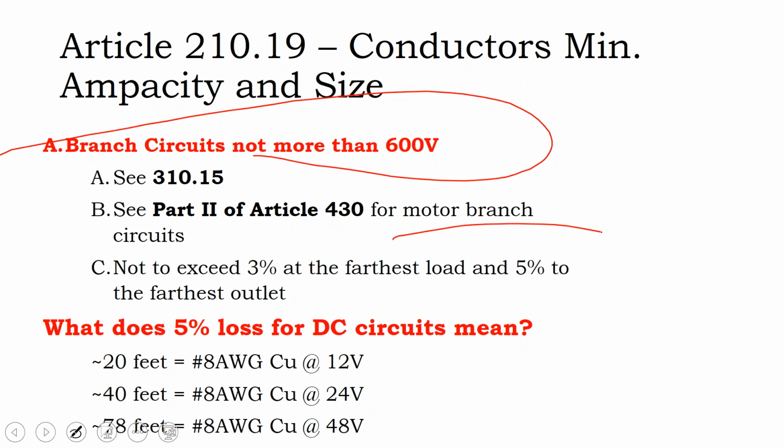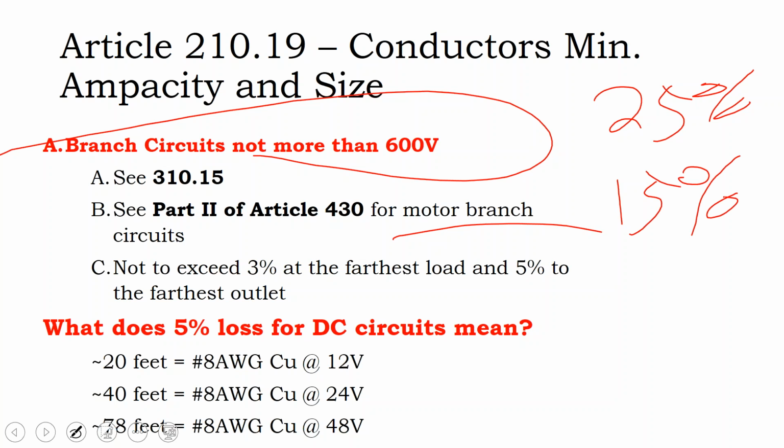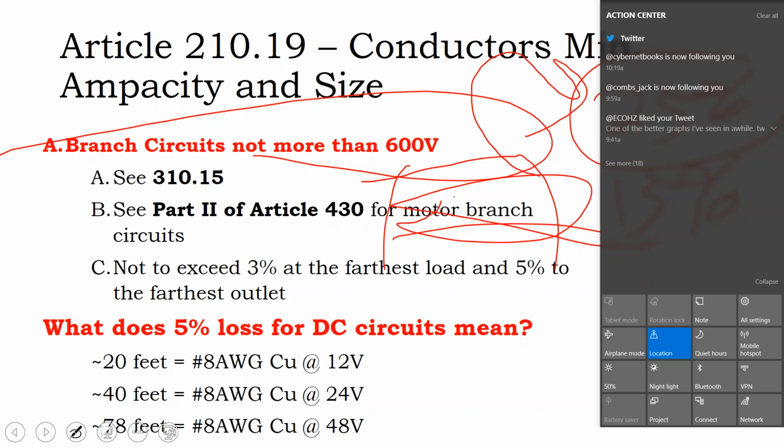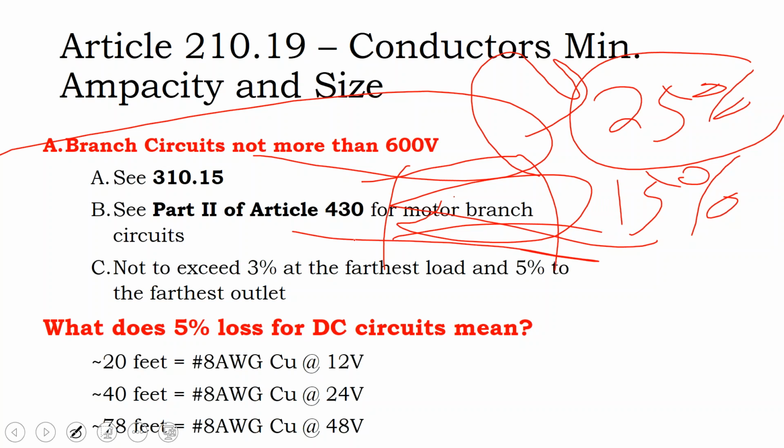Motor circuits are defined later. And generally with motor circuits, instead of having a 25% corrective factor, it might be more like a 15% corrective factor. And often that's because these motors are more controlled than just a dumb continuous load. And so with that extra level of control, maybe there are additional fuse requirements, additional overcurrent safety provisions that are applicable to a generator. So it might not be that the generator's simpler or cheaper, it's that because it's more complicated with more protections built into it, they don't have just this brute, dumb 25% overcurrent applied to it. But that's specialized, and we'll get there.